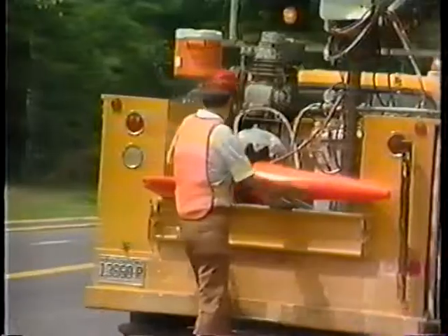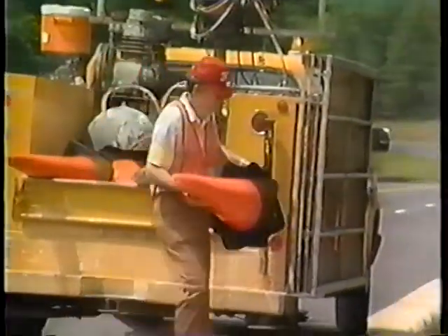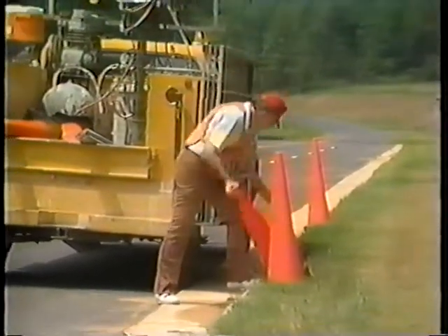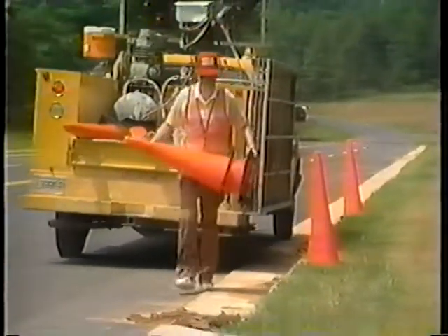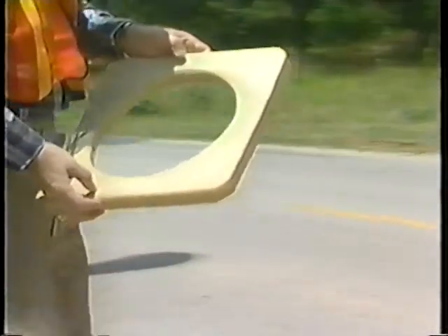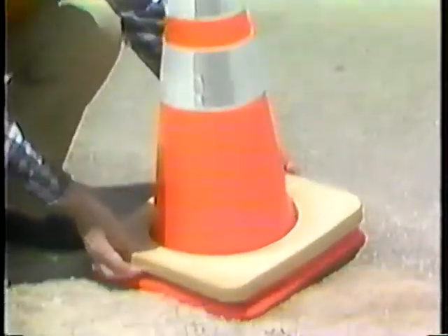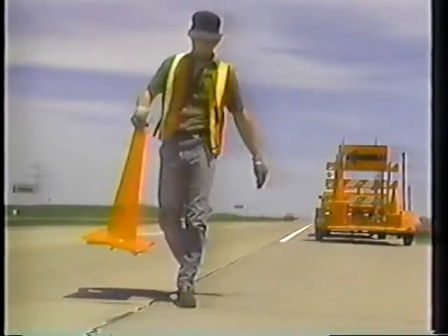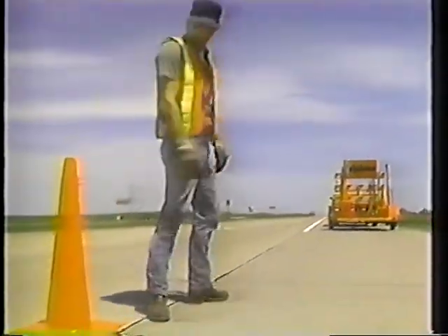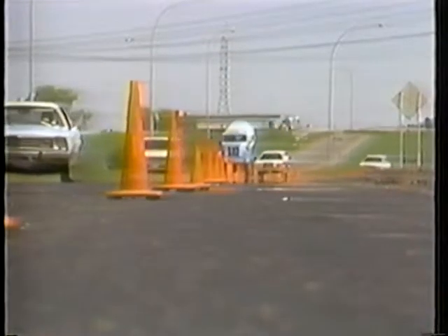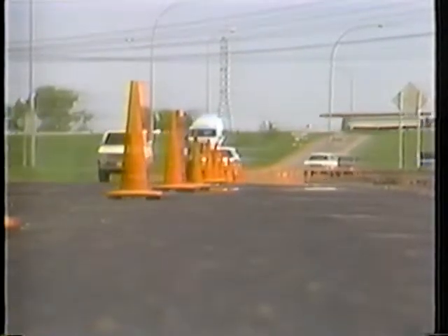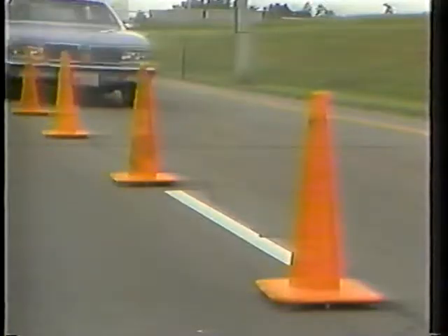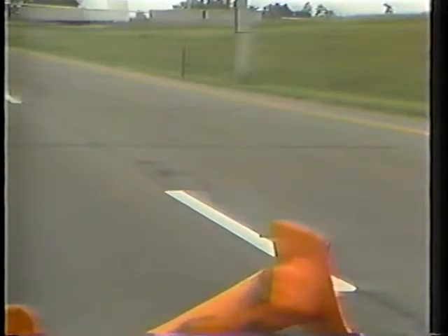Cones are lightweight channelizing devices that may be stacked for storage. They are easy to place and remove and are a minor impedance to traffic flow. For stability, a rubber or sand collar or a specially weighted base may be added. When purchasing cones, specifications may require 60% or more of the weight in the base, thus removing the need for extra base weights or collars. Cones cause little or no damage when hit.